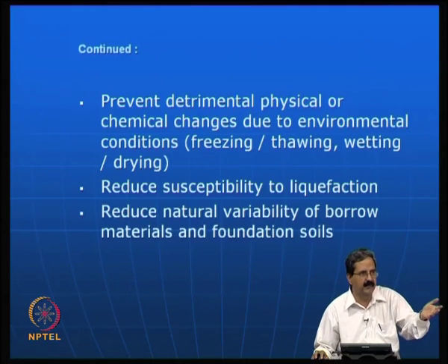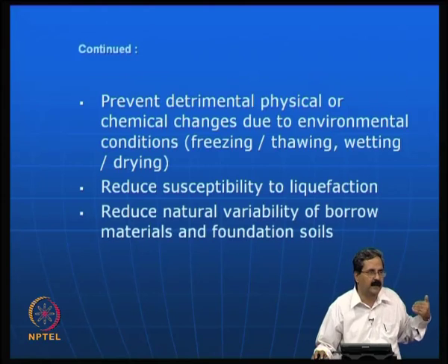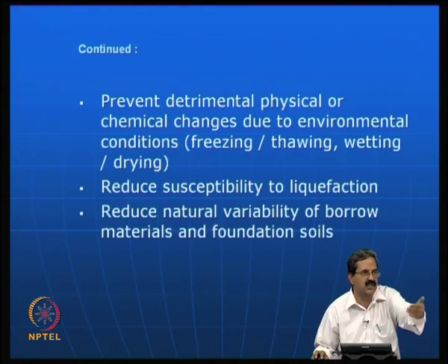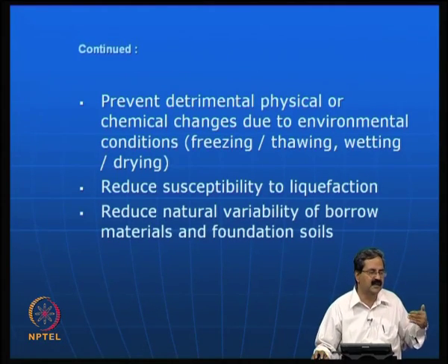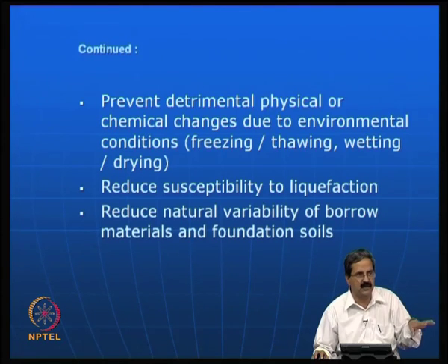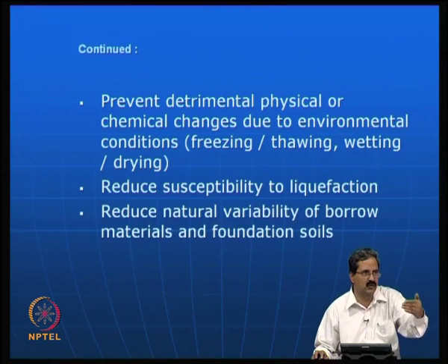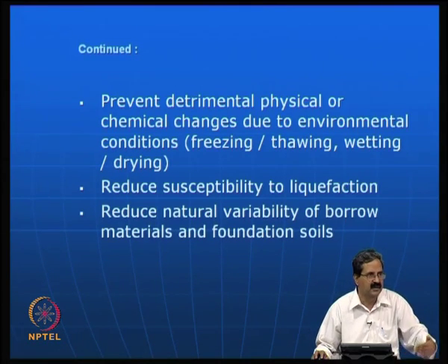Maybe in the next area, there is another borrow pit material, another soil at the next site, and the foundation of the big structure is lying on this soil and then that soil. The way that it should be done is that you should calculate the stress strain response of both materials and compare whether the materials have the same stiffness. These two materials are now two foundation soils, one here and the other there.